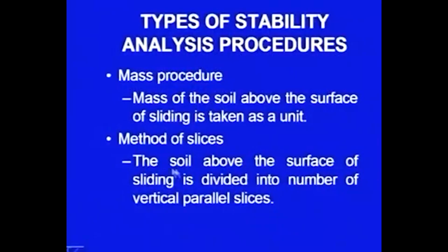In the second method, the method of slices, the soil above the surface of sliding is divided into number of vertical parallel slices. So, this method you can say it will be much more accurate in certain situations. So, here we are not going to take the mass as a whole, we will be dividing it into number of vertical slices to make our analysis more accurate.